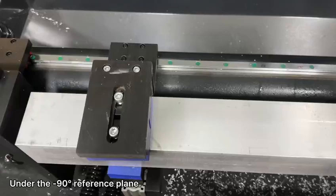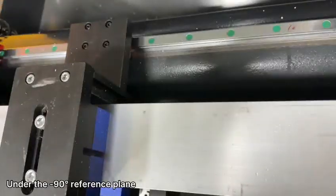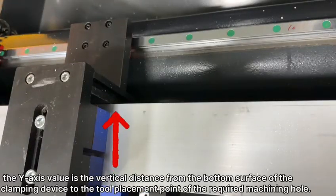Under the -90 reference plane, the x-axis coordinate value refers to the horizontal vector distance from the reference plane of the positioning plate to the tool placement point of the target machining hole. Under the -90 reference plane, the y-axis value is the vertical distance from the bottom surface of the clamping device to the tool placement point of the required machining hole.